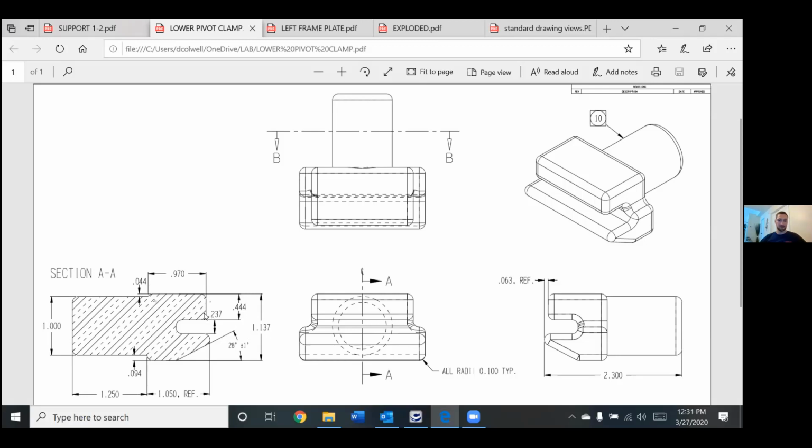If it matters to you how thick this thing is, because it has to have a certain strength, and if its cross section is too thin, it's going to be an issue, then dimension it independently. Don't dimension it from the bottom of the part. But the whole point there was, whenever possible, whenever it makes sense, try to stick with a single datum point.